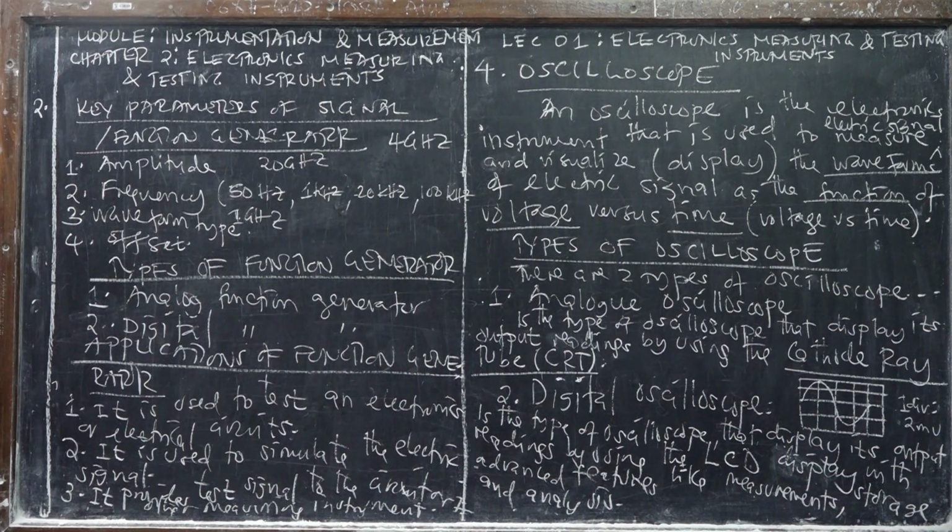But again, with the digital oscilloscope, there are no manual calculations of scale, divisions, or whatever. Once you display the waveform, it shows the amplitude, the root mean square voltage, the average voltage, the frequency, all the important parameters of that electric physical quantity.